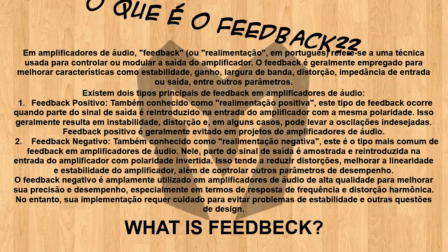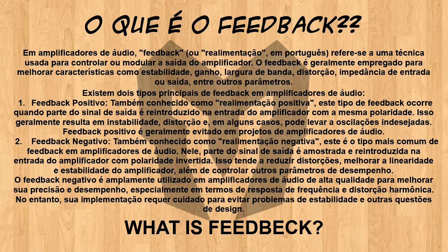What does feedback mean in audio amplifiers? In audio amplifiers, feedback refers to a technique used to control or modulate the amplifier's output. Feedback is generally used to improve characteristics such as stability, gain, bandwidth, distortion, input or output impedance, among other parameters. There are two main types of feedback in audio amplifiers. 1. Positive feedback. This type of feedback occurs when part of the output signal is reintroduced into the amplifier input with the same polarity. This often results in instability, distortion, and in some cases can lead to unwanted oscillations.